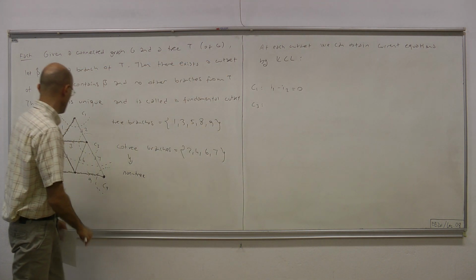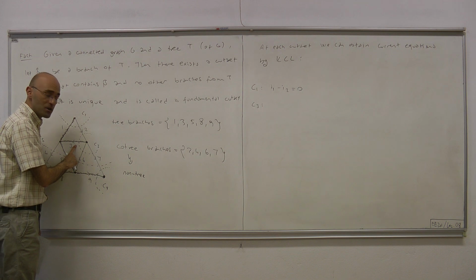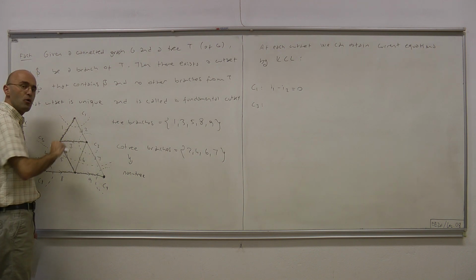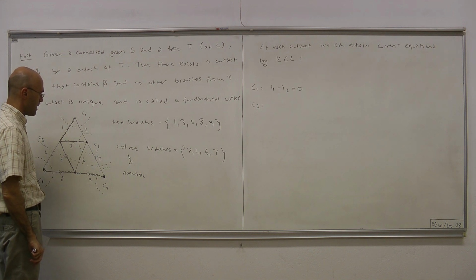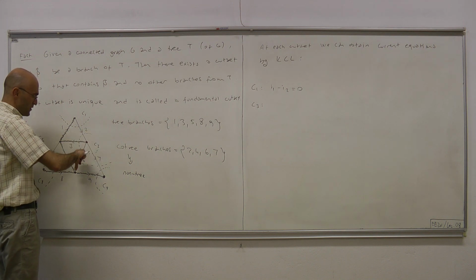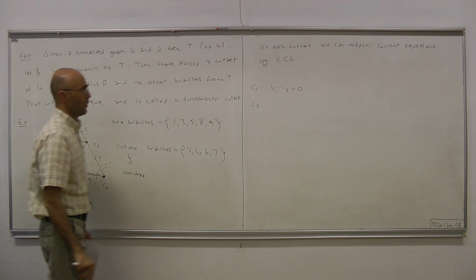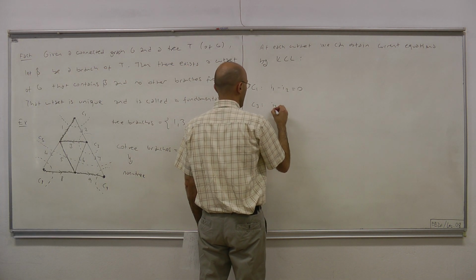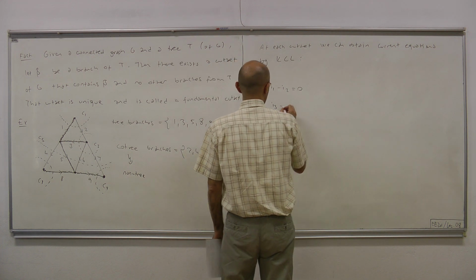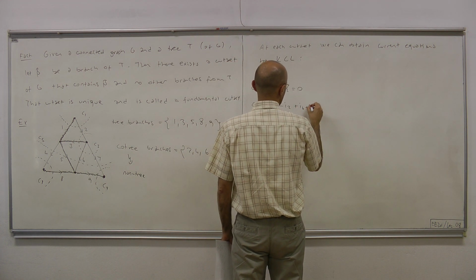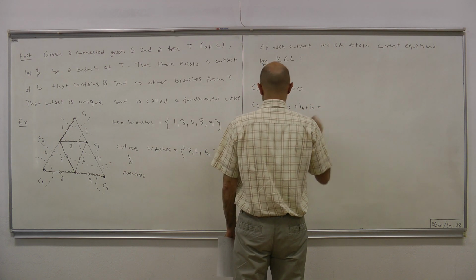C3, this is the tree branch that's associated to that particular cutset. Let's say it's outgoing, so we're going to consider all the currents as outgoing. So I3 is outgoing, I6 is outgoing, I7 is outgoing, and minus I2 is outgoing. So we have I3 minus I2 plus I6 plus I7 equals 0.